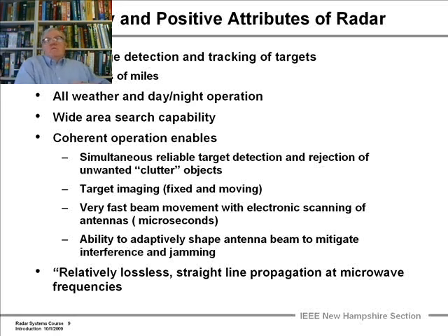You don't have to move a big antenna, some of which I'm going to show you are hundreds of feet in diameter. So you don't have that mechanical inertia to point the antenna in different directions. You can electronically scan the beam in microseconds. And you also have the ability to adaptively change the shape of the beam so that you can mitigate interference and people jamming the radars with unwanted extraneous noise.